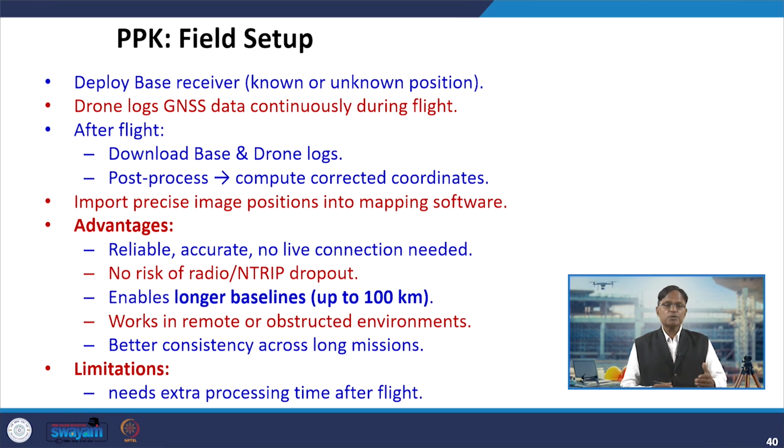So this slide shows the steps involved when we are doing the field setup. We will deploy the base receiver, a known station whose coordinates are known to us. The drone will log the data, and after flight we will download the data and process the data.